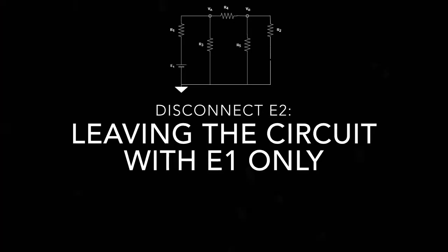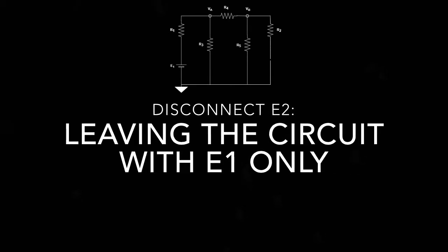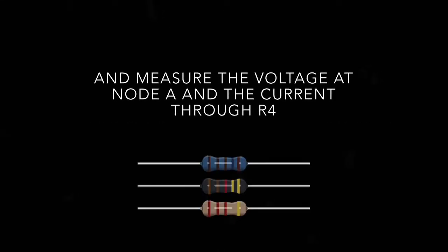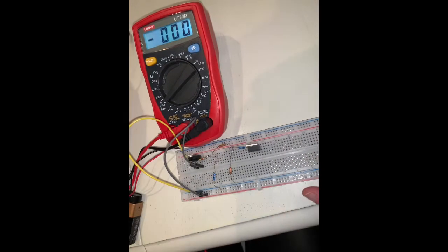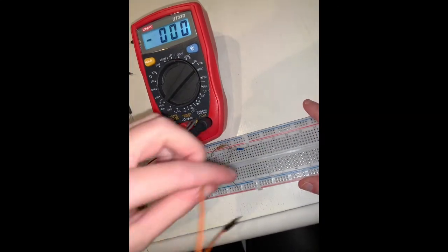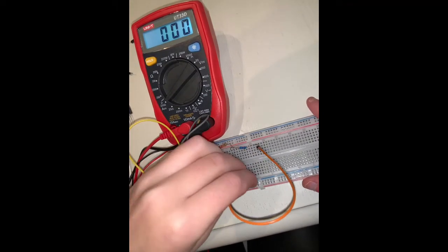Let's disconnect the E2 or the 5-volt voltage regulator and replace it with a short circuit and measure the voltage at node A and the current through the 22 kilo resistor. We begin with disconnecting E2 completely from the circuit and replace it with a jumper wire.